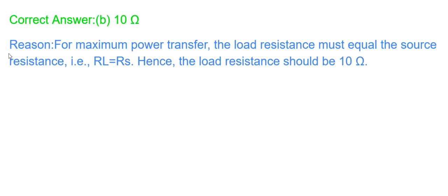Correct answer is B, 10 ohms. Reason: for maximum power transfer, the load resistance must equal the source resistance, that is RL equals RS. Hence, the load resistance should be 10 ohms.